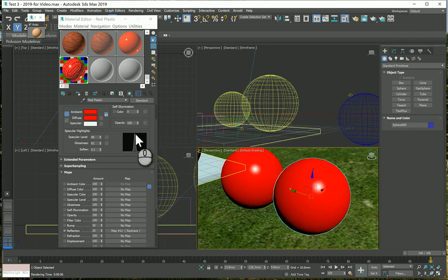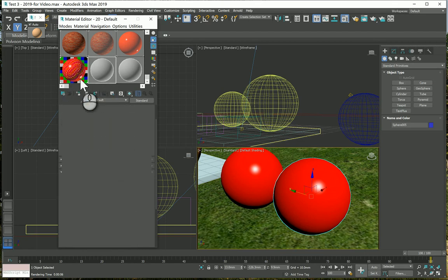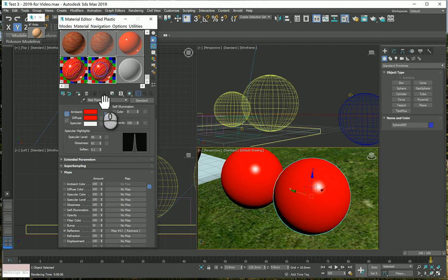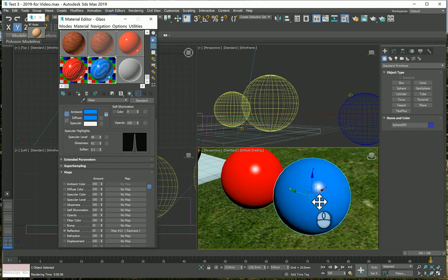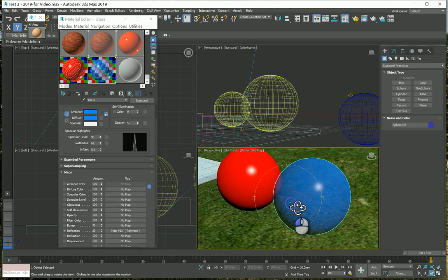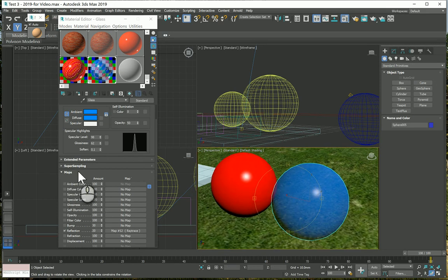So if I want to make this glass, let me just drag and drop that. When you drag and drop the element, you're going to copy it here. Make sure, my dear, that renaming is super important. I'm going to change the basic color to blue, drop that in here, and for the opacity I just need to add a value, let's say 50%. This is a very basic type of opacity, and there are actually much better advanced techniques to do that, but this is the fastest one and the lightest one on our machine. I think that will do the job properly.